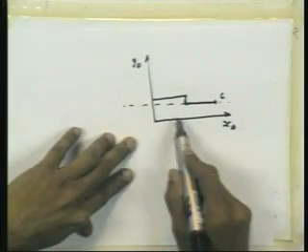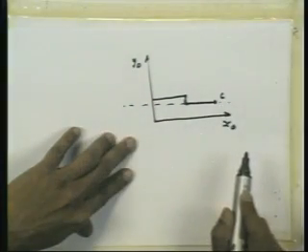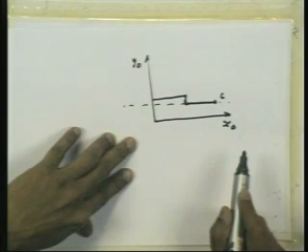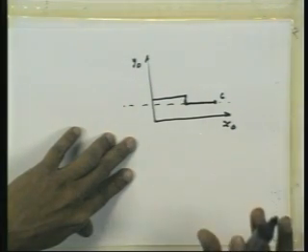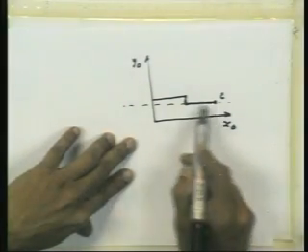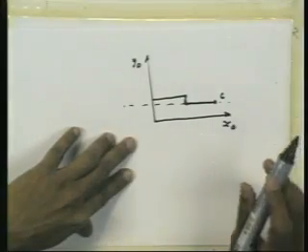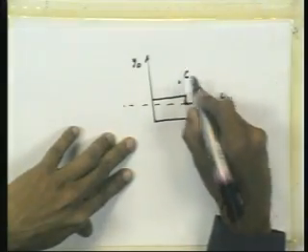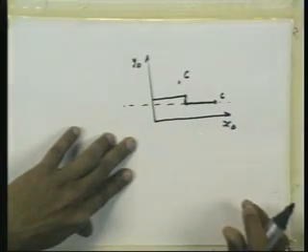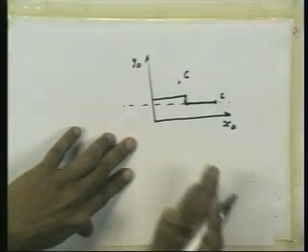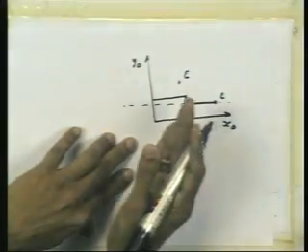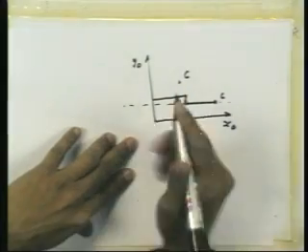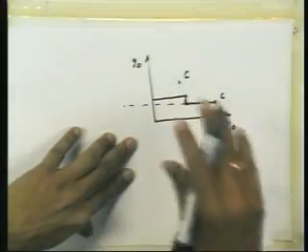Theta 1 rotates the entire thing. What theta 1 does is position this particular plane. Suppose the point C is actually here, the given position is here. What theta 1 does is bring this plane into coincidence with this particular point, its projection in the xy plane.